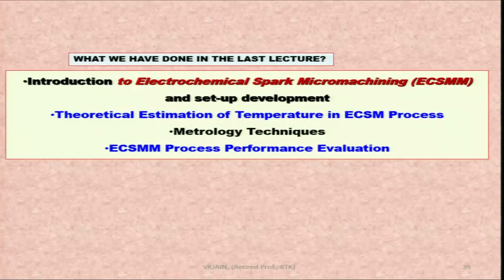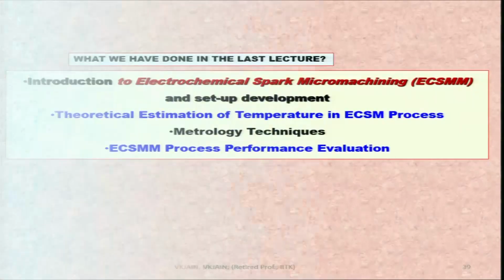Electrochemical spark micromachining process performance evaluation also we discussed. It can be evaluated based on the depth of the features created, width of the feature created. If it is a channel, then overcut on the feature created.